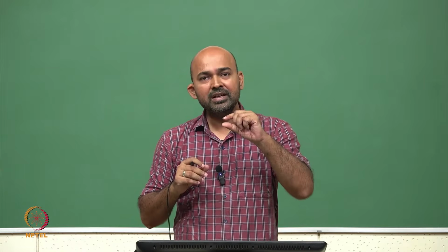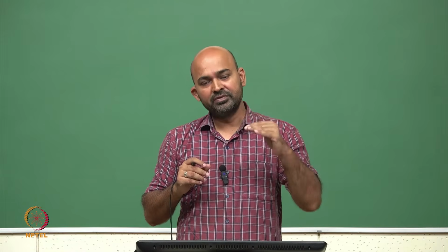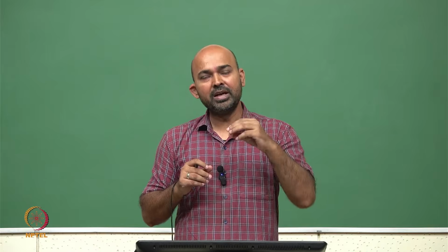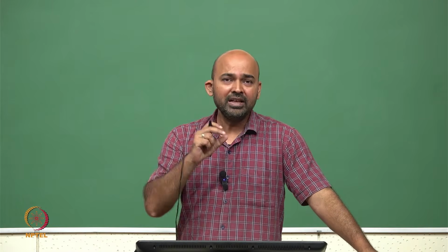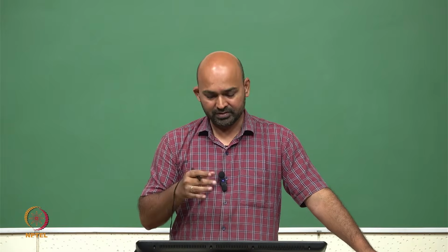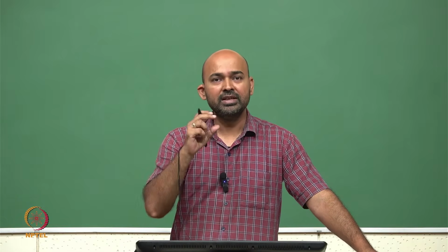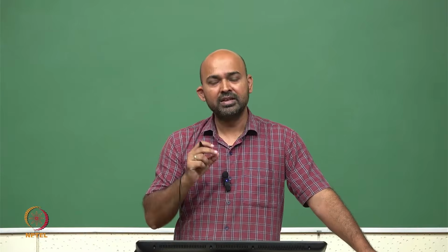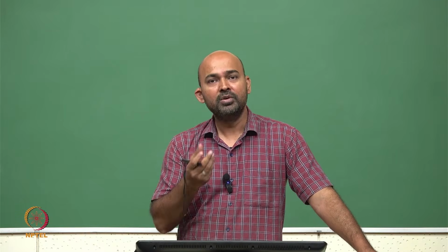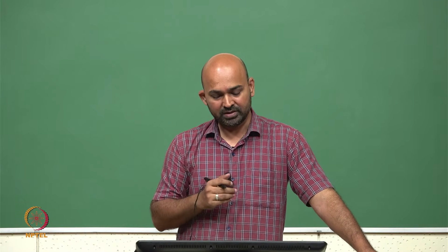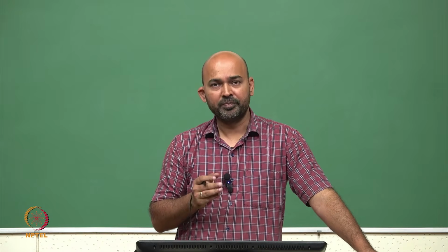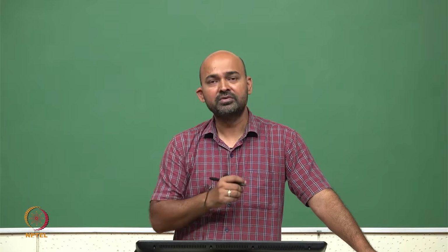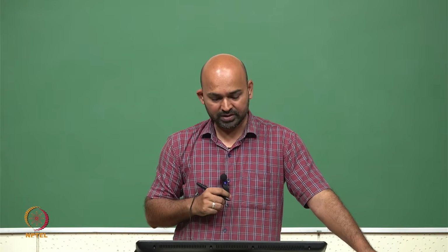However, the thickness of the metal we deposit on the substrate to make these wires, that T we cannot reduce after a certain point. So T is still significant, and W has gone very low. So aspect ratio nowadays is almost 2, which was very much less than 1 in older technologies.